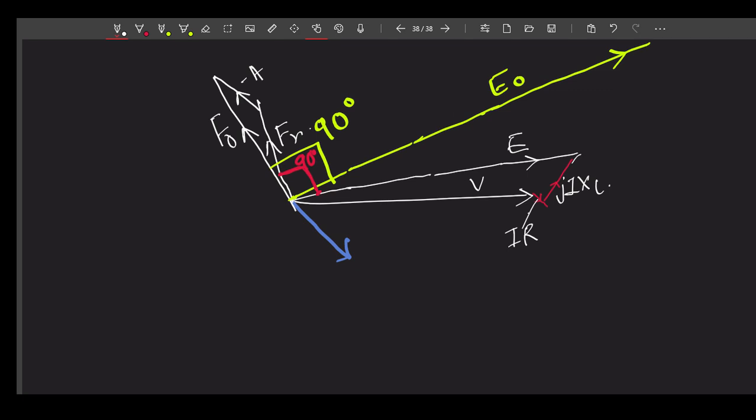Once you get this detail, or means draw this phasor diagram, is where xd and xq are required, when you need to draw something like this. Means when you are trying to represent armature reaction MMF by means of a virtual reactance, then only you need xd and xq. This will become jxd id, this will be jxq iq. Otherwise, it is not required.